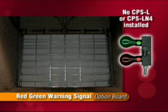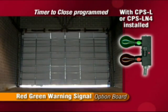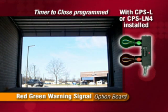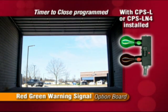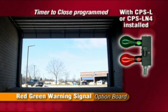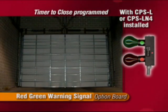close limit is activated. Combined with the CPS-L or CPS-LN4, and when a timer to close is programmed, the green light will turn on when the door reaches its full open position. The red light will turn on 10 seconds before the timer starts to close the door and remain on until the close limit is activated.